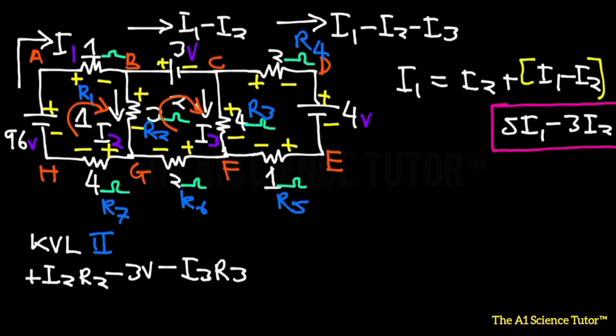Now like I told you, the parallel first half of this section is this one. And the current that goes through that section is I1 minus I2. So that is going to be the same current that goes through the 2 ohms resistor. So you really just got to hold that at the back. So the 2 ohms is going to receive a current of I1 minus I2, and that ends on a negative note.